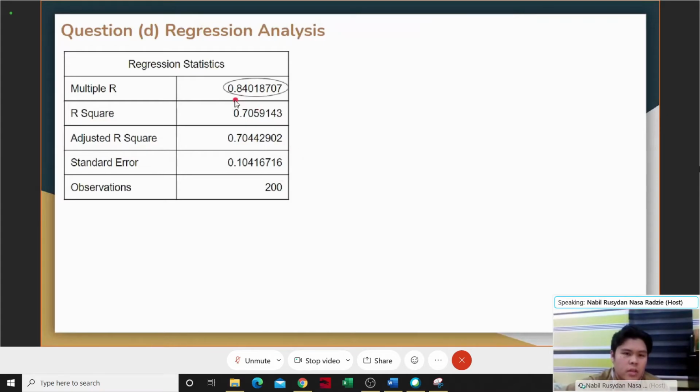As we can see, the R value is close to +1, which indicates it is less scattered and has a strong positive linear relationship between the relative density and the tensile strength, while the R square indicates that around 70.59% of the data fits the regression model, which can explain the value of the tensile strength and shows that the simple linear regression model is adequate to explain it.